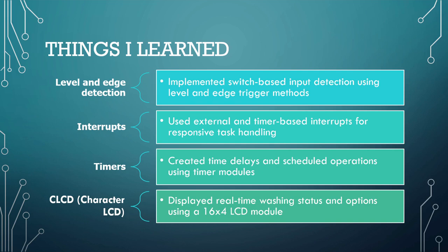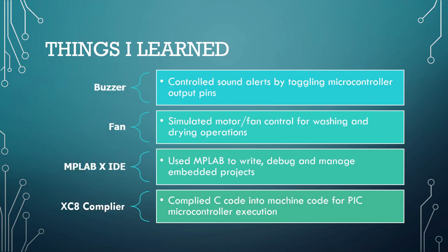A big part of the user interface was CLCD, that is the character LCD display. I used it to show the selected mode, water level, and current washing status. I worked with a buzzer which acts as a notification alert when the cycle is complete, and a fan that simulates the washing motor during operation.